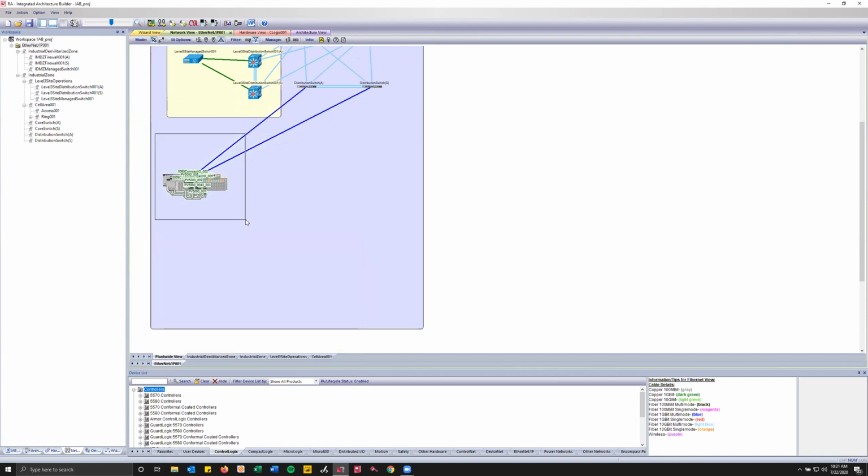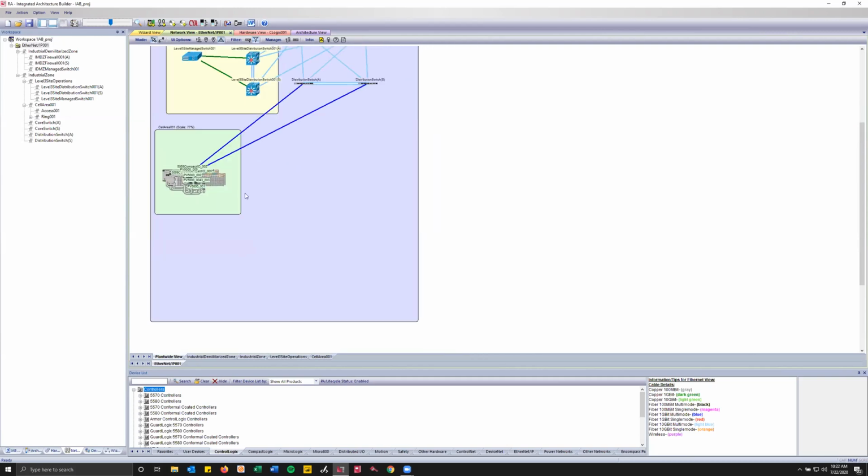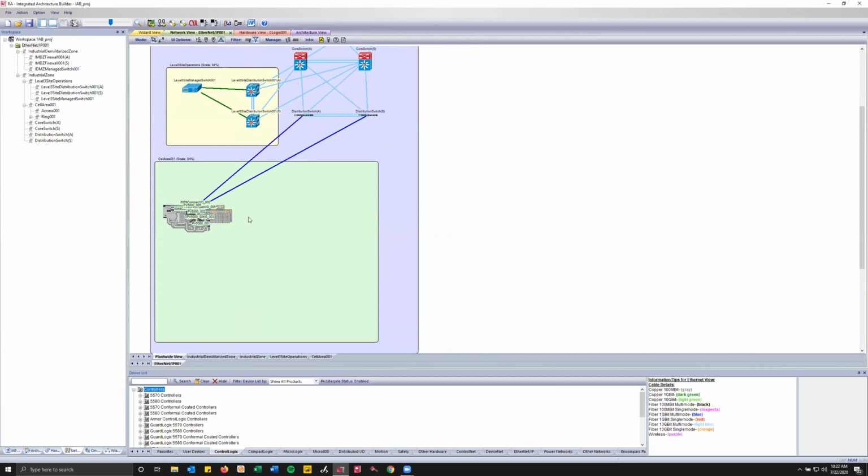So if this was down here, the scale might get smaller and smaller, and you might not be able to see anything you're working with unless you start zooming in with your slider button at the very top. So one option that they've given in your right click menu is maximizing zone scale, and it will make it as big as it can make it within the view to come in line with everything else on that page.